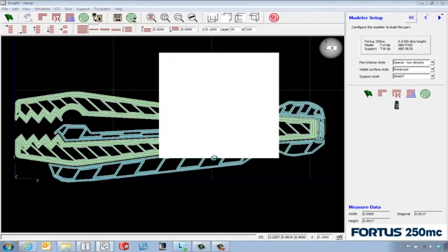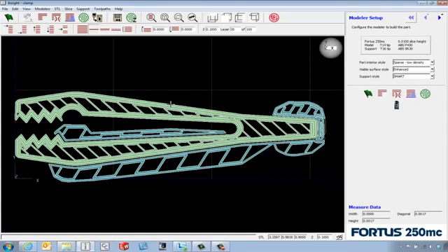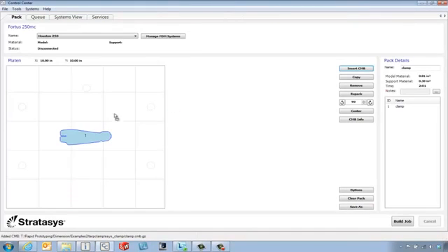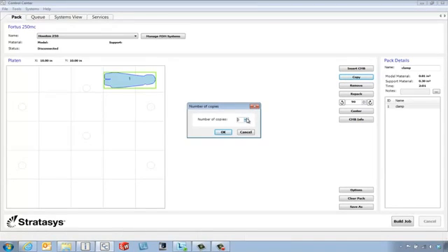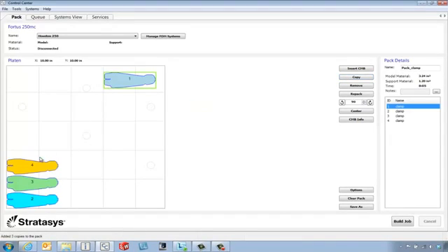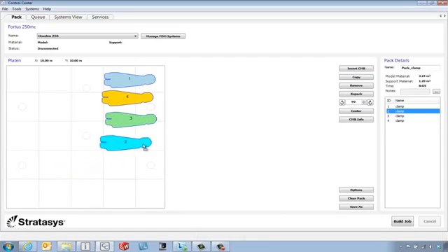When we get into Control Center, we've got the ability to move the part around in the build platform. We've also got the ability to make 3 or 4 of these, and we can move them around however we like. And if we're connected to the machine, we can say build job, and this will send the part to the printer just like it would a regular network printer.